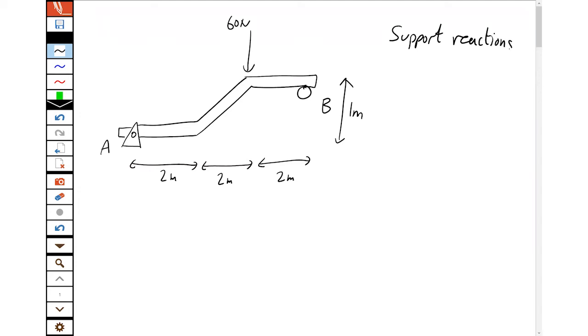Well, the cool thing is, a huge swathe of this course is all just the same equilibrium problem, where you have a free body diagram, then you do the moment and the force equations. So let's do that. First, we want to get our free body diagram ready, which means adding the support reactions. Now, A is a pin, so it has a vertical reaction and a horizontal reaction. We don't know if they're actually in the positive directions, so we just say they are, and then the math will tell us the actual answer. B is a roller, so there's a single force reaction there.